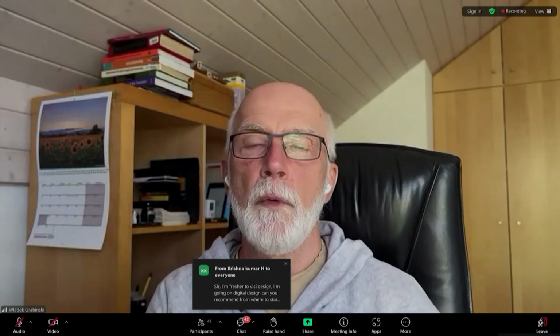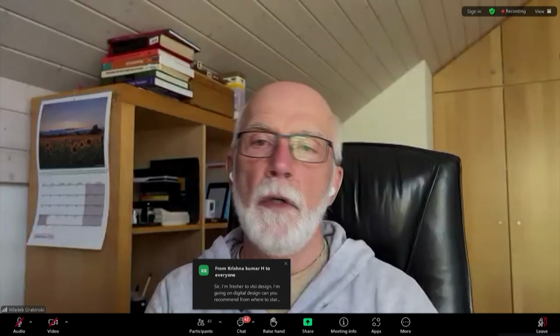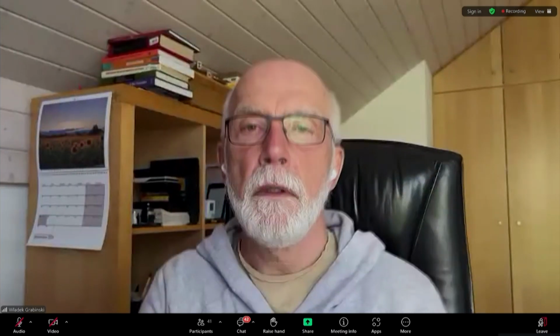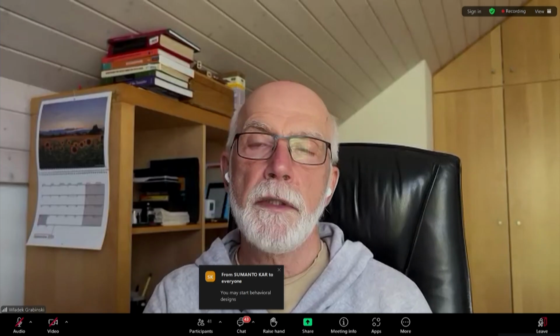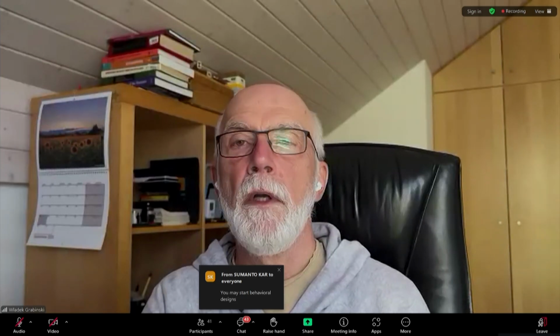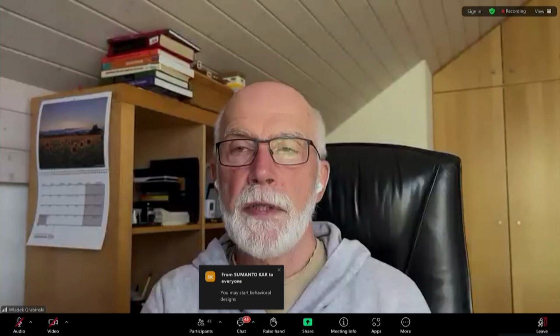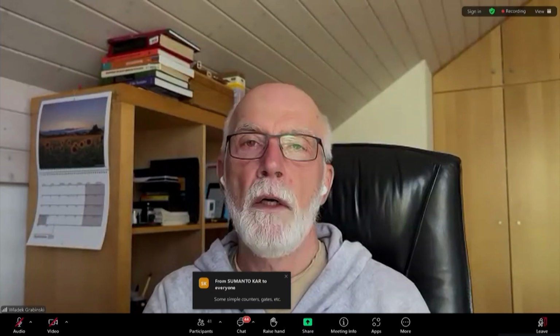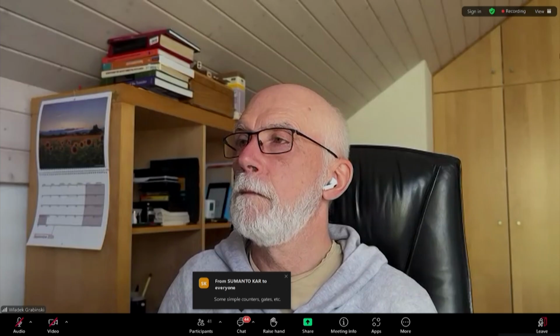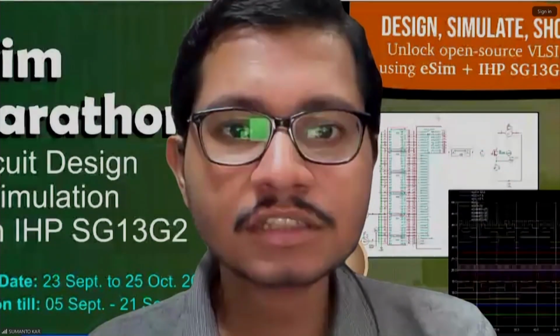Maybe if you want a more technical discussion, just use my email and submit your questions. So Verilog-A or Verilog-AMS is not fully supported. For digital simulation, we have full sub-circuit Verilog simulators, but not with the A or AMS option. I hope all the questions are answered.